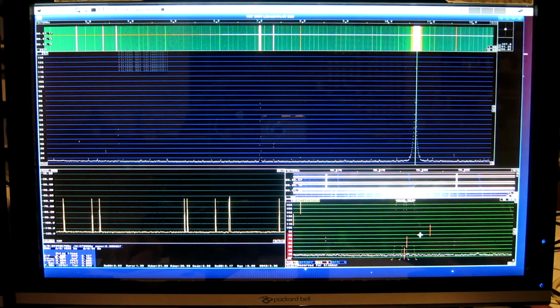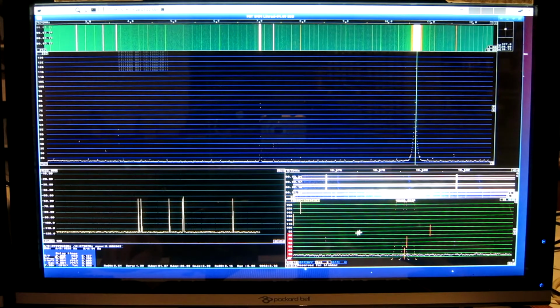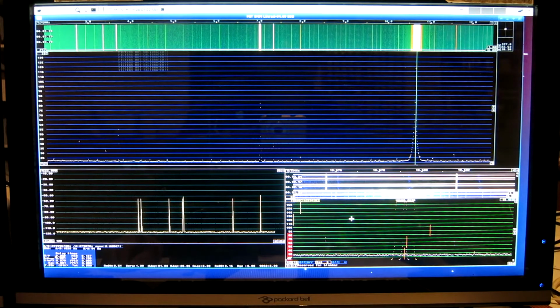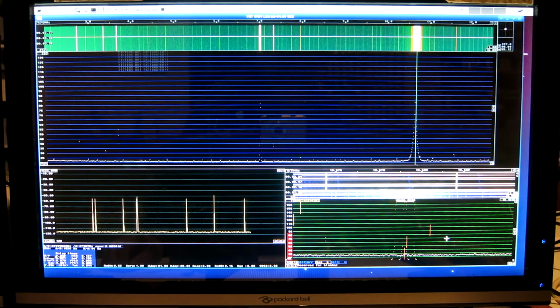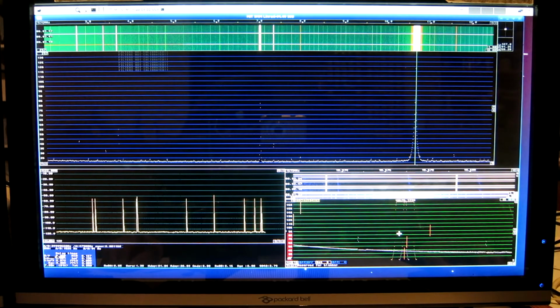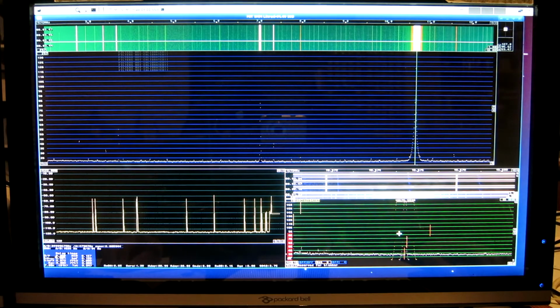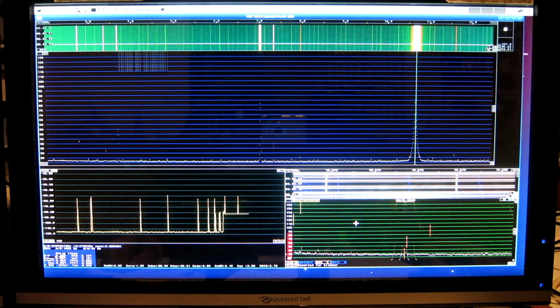If I go, now you can see other things. Here is a spur. It's a resampling spur because at these high sampling rates and with the current hardware and programming in Linrad, I cannot apply appropriate windows to suppress these spurs better. The level is, as you can see here, minus 82 dB. It's not a strong spur.